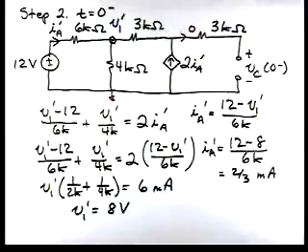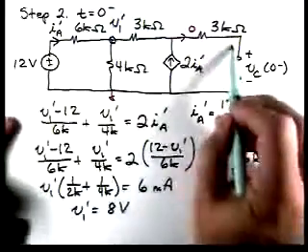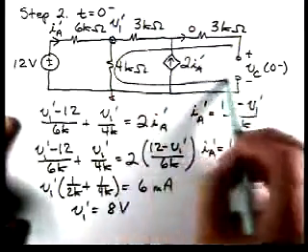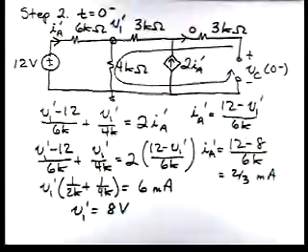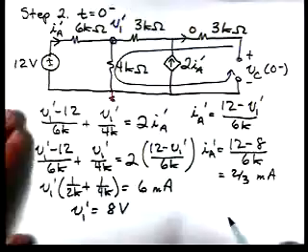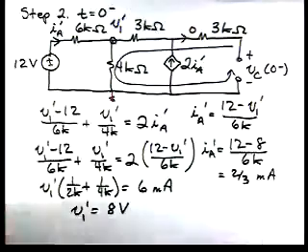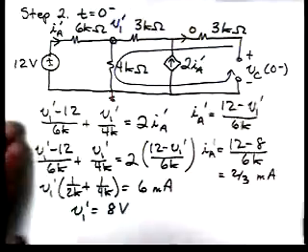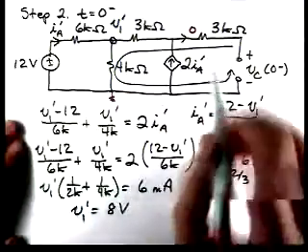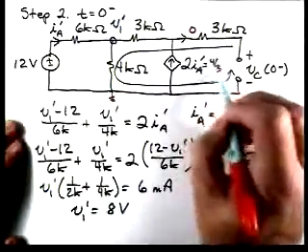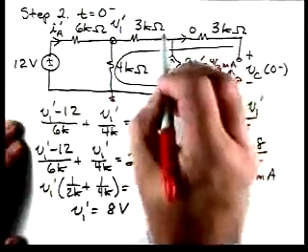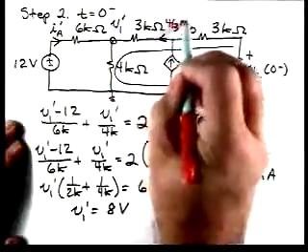Now, to calculate that capacitor voltage, we can do KVL around this loop. So, for instance, if we look for a second, this source has a value of 4/3 of a milliamp then. So there's 4/3 of a milliamp here in the circuit.